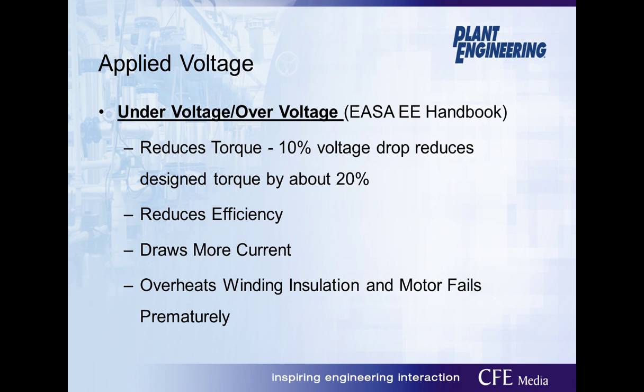It is also worth noting here that most low voltage motors are typically rated at 460 volt, but grid voltage coming from the power provider may be 480 volt. The 460 volt rating is taking into account a voltage drop in the transmission lines coming from the nearest substation or distribution transformer. We have actually completed testing in our lab here at Advanced Energy, verifying that a slight increase in supply voltage above rated nameplate voltage will actually lead to increased motor efficiency.